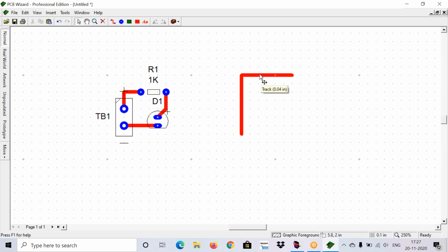Because there will be a loss in the etching process. I will post the theory related to this. But make sure that there is no 90-degree angle in your layout. For simple circuits you can easily design the layout, but for large circuits you may use a 90-degree angle. That is not recommended, so you never.